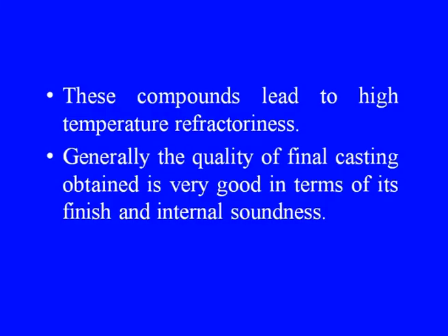The applied coatings produce stable compounds of titanium oxide, ferrous oxide or aluminum oxide, which depends on the type of sand used. These compounds lead to high temperature refractoriness. Generally, the quality of the final casting obtained is very good in terms of its finish and internal soundness.